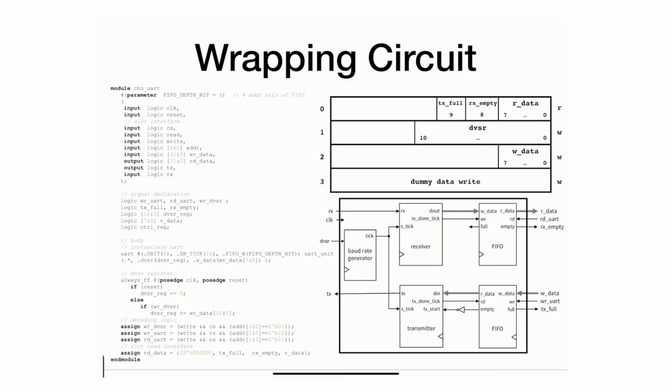So why do we do this? The reason is this read FIFO in here. Remember, the first word fall through, that write data is actually available all the time in here, and I can move to the next line or the next value in the FIFO by issuing some sort of a signal in here. So I'll have to figure out when to issue it exactly, and there's some weird timing things that the processor needs to deal with. So technically, I can just take this and make it into a write and do the decoding into it and whatnot. But I think it's just easier to write this dummy data in this particular register, and that's it.